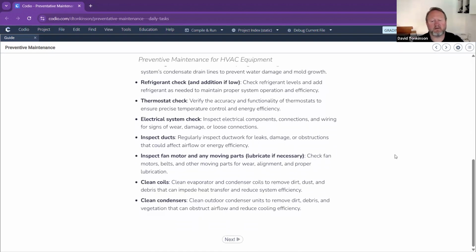And it's worth checking the thermostat. We know the thermostat is basically an electronic device. Okay, it is possible that electronic device is faulty and it's reporting the wrong temperatures. So we can go along either with a thermal imager or with another thermometer that we've calibrated previously, and we can check to see that that thermostat is basically producing the right temperatures.